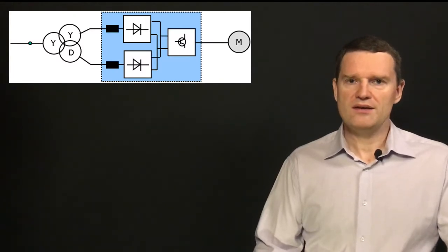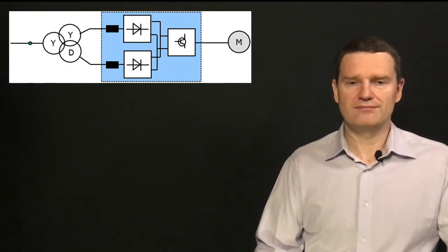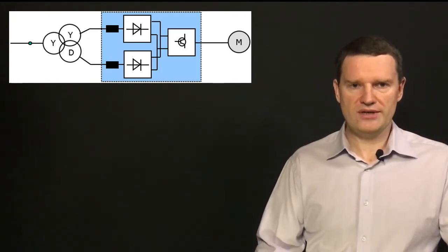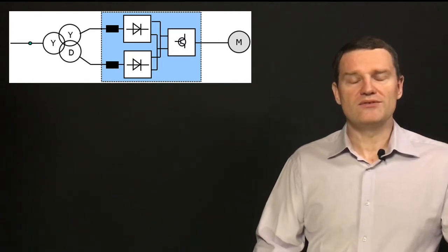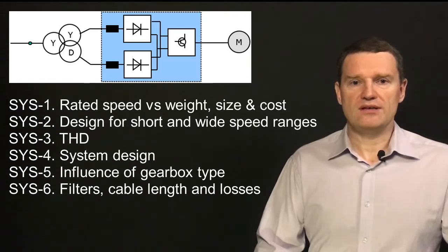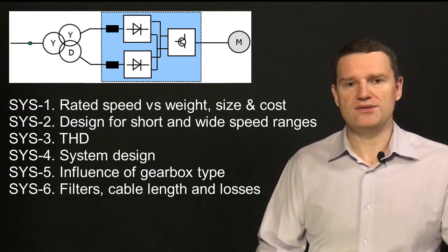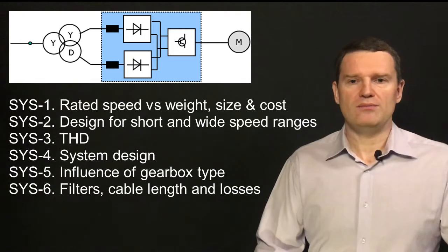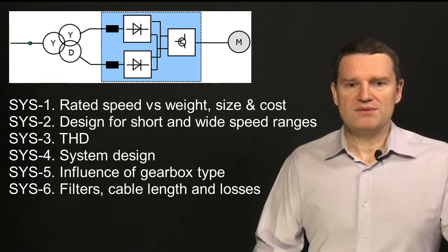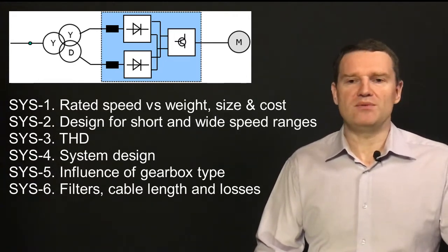The third group of exercises is on systems. Here the machine and the converter are considered together. The knowledge we are after here is how to choose not only the right machine or the right converter for your applications, but the right combination of them. Going through these 6 exercises, we learn thinking of both mechanical and electric sides of the drivetrain. We learn, for example, that the system can be designed in a smart way, minimizing size and cost of its components, by choosing optimal relationships between the required load and the system capability across the speed range.